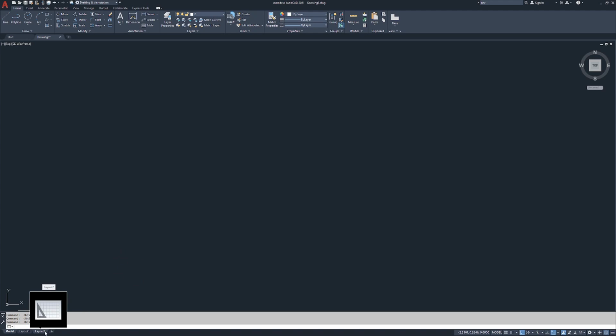So if I want to draw a circle, I'm going to type CIR. I'm going to hit enter. Your enter key is going to be how you engage commands in the command line. Your escape key cancels out of whatever command you are in. This is not the same as the buttons up top. So if I click the circle button, I don't have to hit enter because I didn't type anything in. AutoCAD knows that because I clicked the circle button, I actually want a circle. I'm not unsure of myself. Just let me draw a circle.